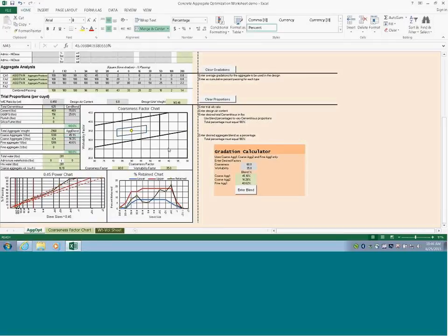We recommend water and optimized mix. Water cement ratios are going to be lowered. Depends on the mix, but yeah, that's a possibility, and there's less water demand with an optimized aggregate mix. Right. That's a possibility with the mix. It depends on all the components, but yeah.